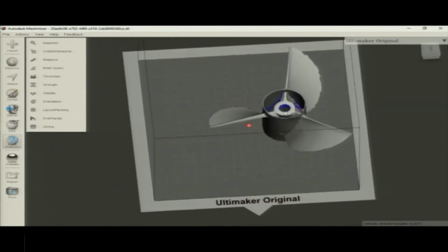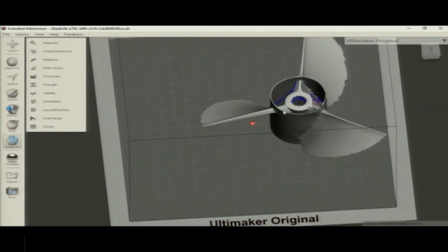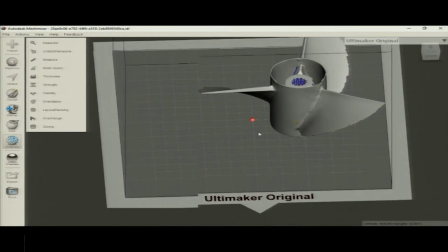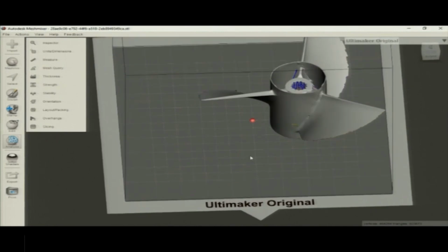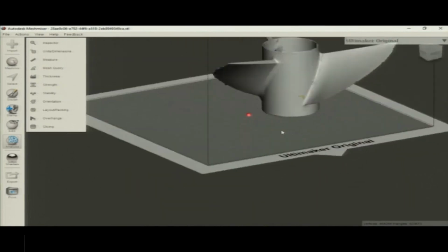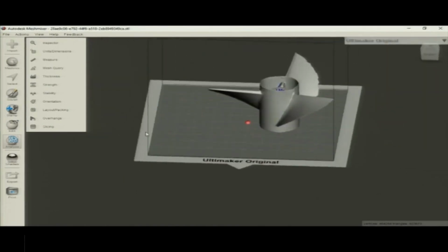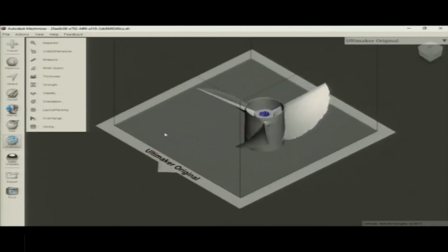You can see here, this is a very fine boundary which is placed over the print bed, and this very small thickness wouldn't have strength to stay on the bed. So, it might pop off. So, we need to consider all of these conditions like brim or raft, what is to be put in here.